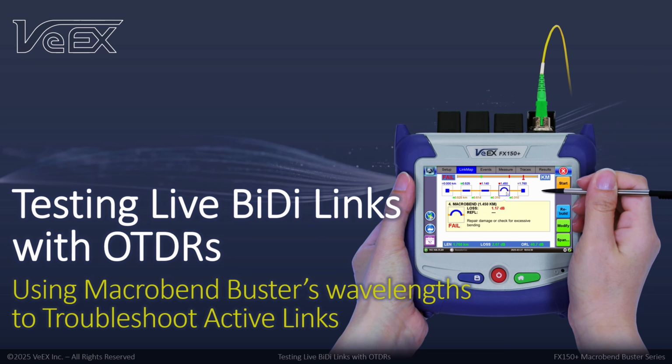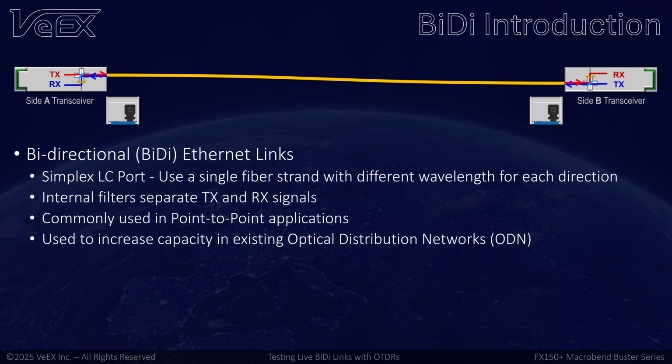This video covers troubleshooting live BiDi links with OTDRs and explains the need for specific wavelengths to avoid disrupting other services or affecting OTDR measurements. Commonly used for point-to-point links, bidirectional transceivers have a single fiber connector to transmit and receive, using just one fiber optic strand. They can help optimize fiber utilization on existing optical distribution networks and increase capacity.